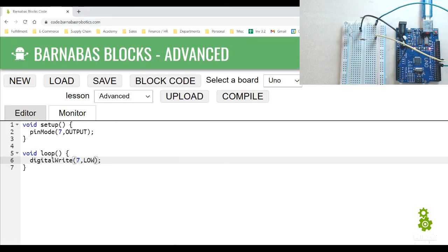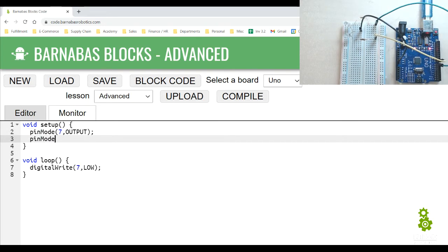All right, let's get my code here. So the first thing we want to do is set up the pin mode. Which pin are we using? Pin number 8, and we want output, because this is just a second LED, the same exact thing. There will be a time where we have to make it an input, but because it's the same type of part, it's also an output.